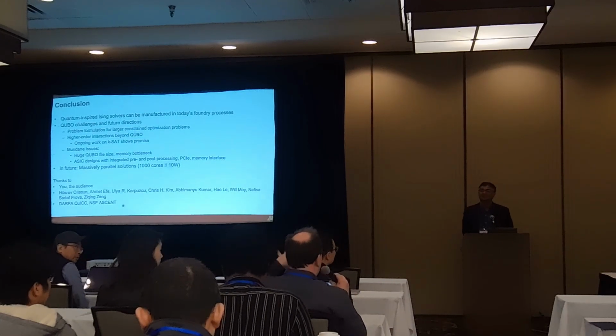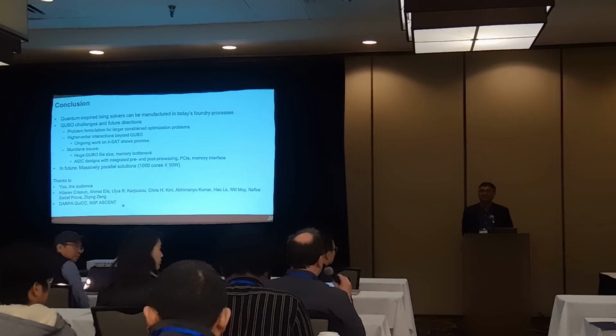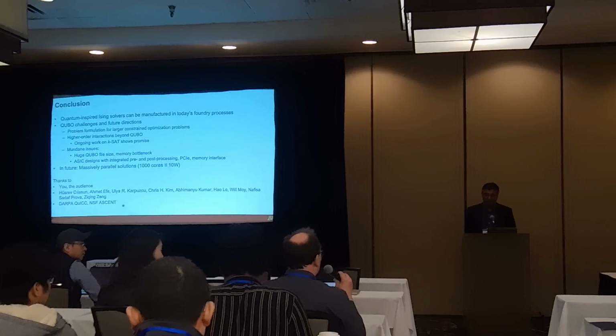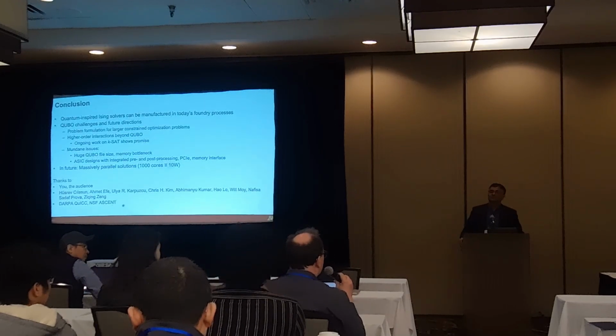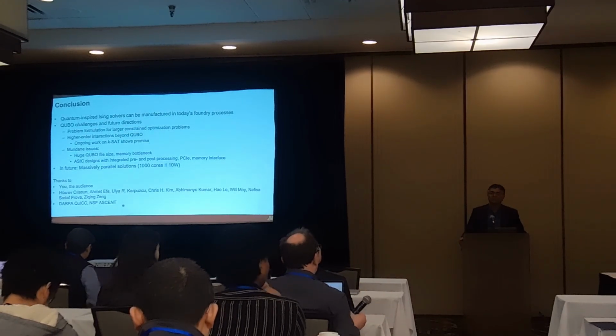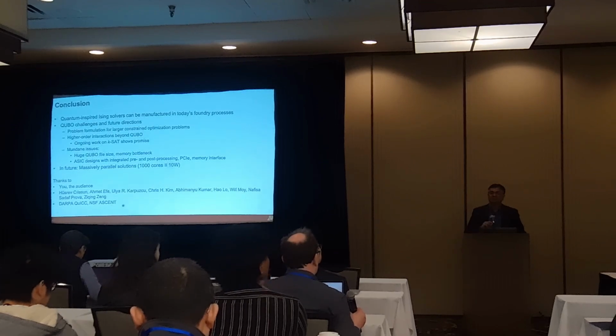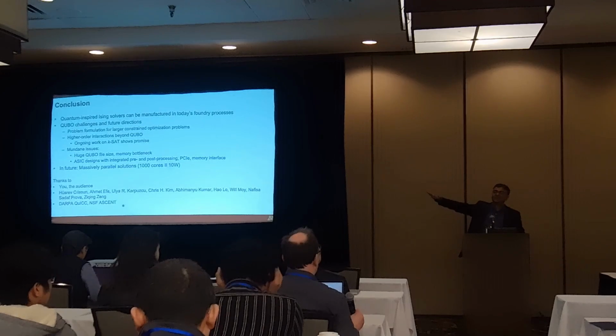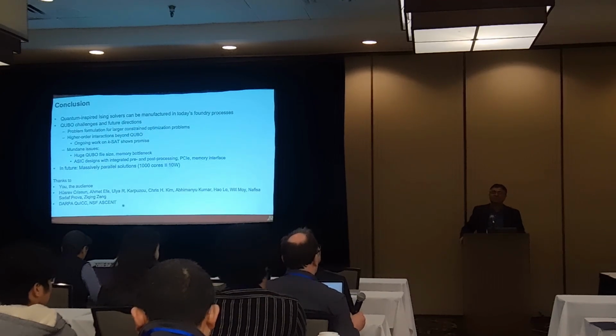So you can entangle all 58 bits. Yeah. So I assume that the chip size still increases if you add more bits. What do you see as a natural limit? What's the number of bits that you might be able to do? We've gone up to 70 or so, and I think going much beyond that is going to be problematic because your coupling also weakens, because you're taking a signal all along the ring oscillator. So the more stages you have, that's the number of coupling sites you have. So I would be very surprised if it went beyond 100. I think 50 to 70 is the optimal, and then decomposition is the solution.